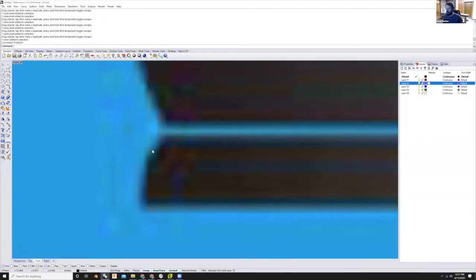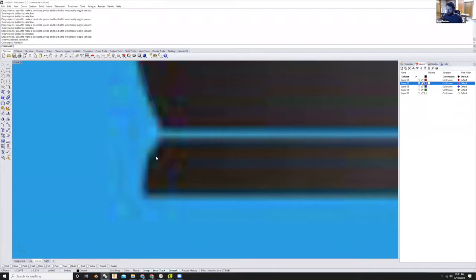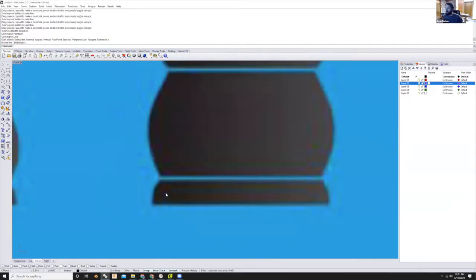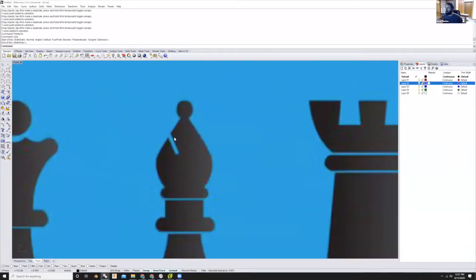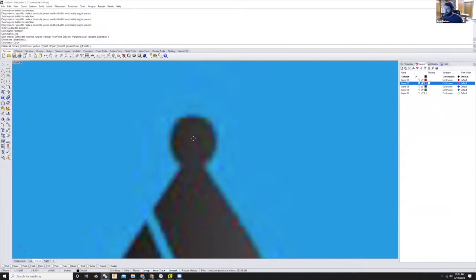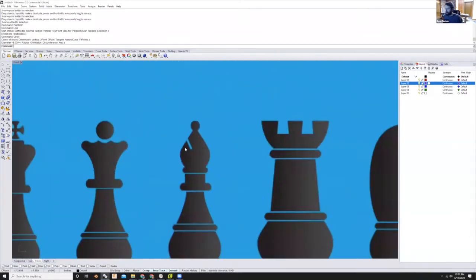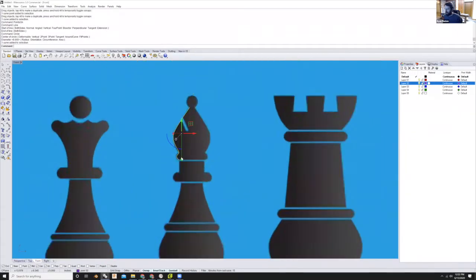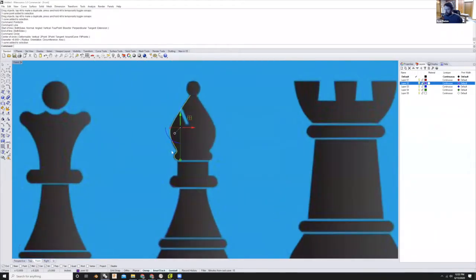I'm going to do a vertical line here. So type line, click this endpoint, and holding shift, I can go down to about here. And that is pretty good. I want to do a circle up here now, so I will type circle. And roughly at the center point, make a circle. And now we have our basic geometry drawn here.